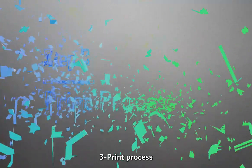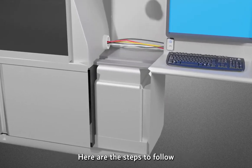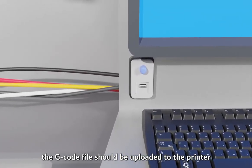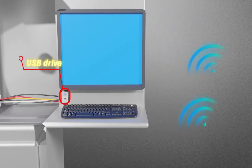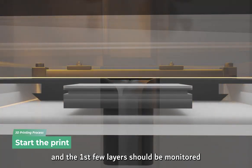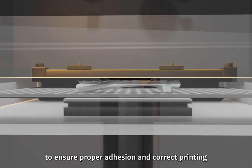3. Print process. The print process is the heart of the matter. Here are the steps to follow. Firstly, the G-code file should be uploaded to the printer by connecting it directly to a computer, using a USB drive or via Wi-Fi. Once the file is uploaded, the print can be started, and the first few layers should be monitored to ensure proper adhesion and correct printing.